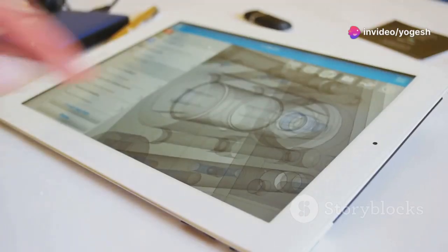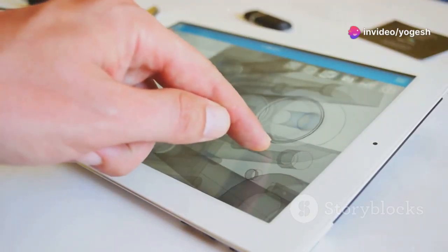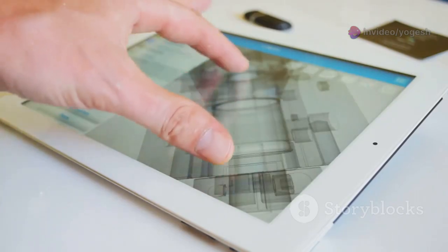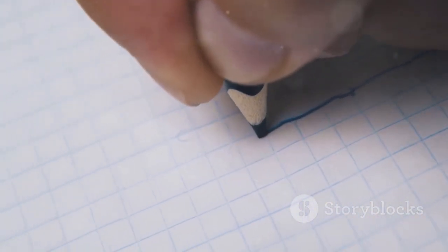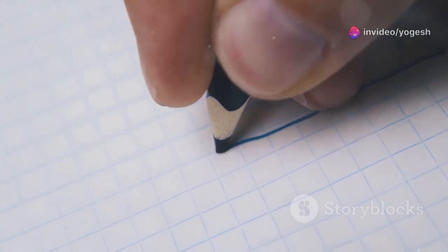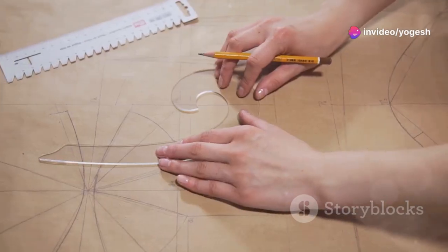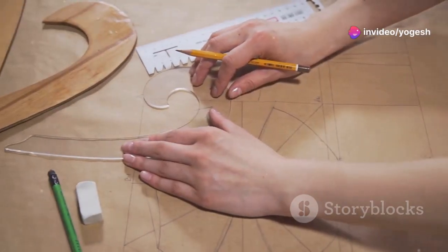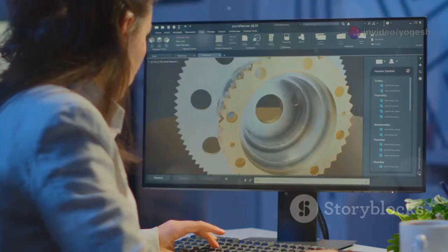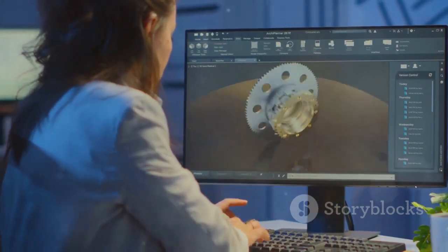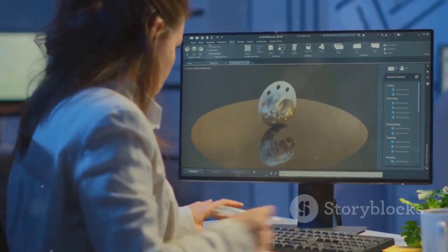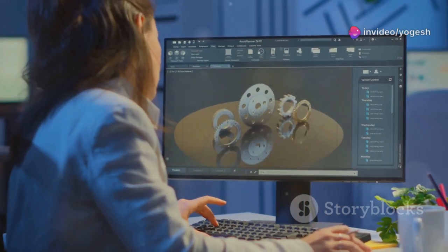With a simple arc, you get one control, the radius. That's it. The shape is fixed and can't be adjusted beyond making the arc bigger or smaller. With a spline, you get many. Each point is a handle for shaping the curve. You can add, move, or remove points to get exactly the shape you want, no matter how complex. This is what makes splines so powerful in modern design. They're the secret behind the smooth, flowing lines of everything from cars to consumer electronics.